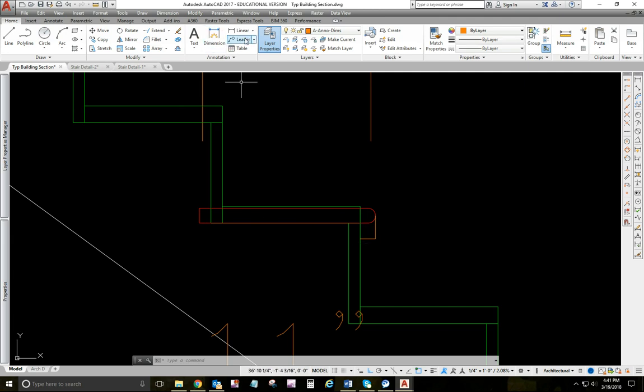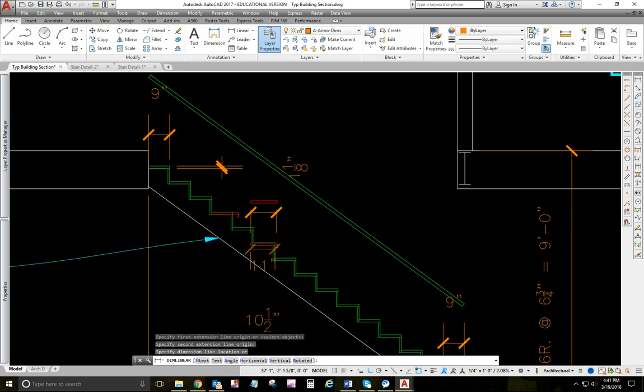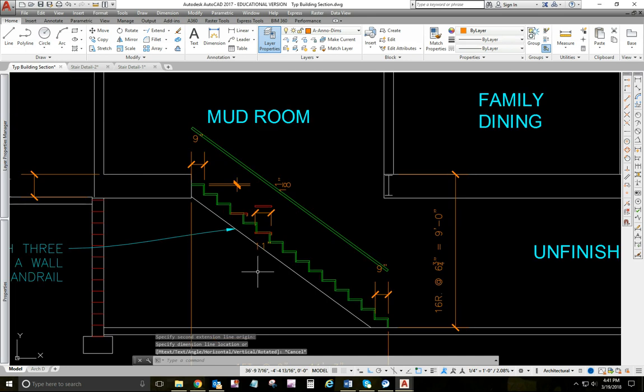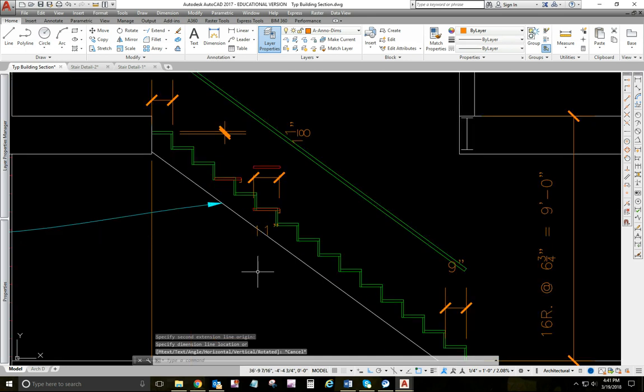Well, when I measure from here to here, that gives me 10.5 inches that I have available that I can use. That's why I say residential treads are rarely more than 10.5 inches in design. In construction, they are, yes, but in design, no.